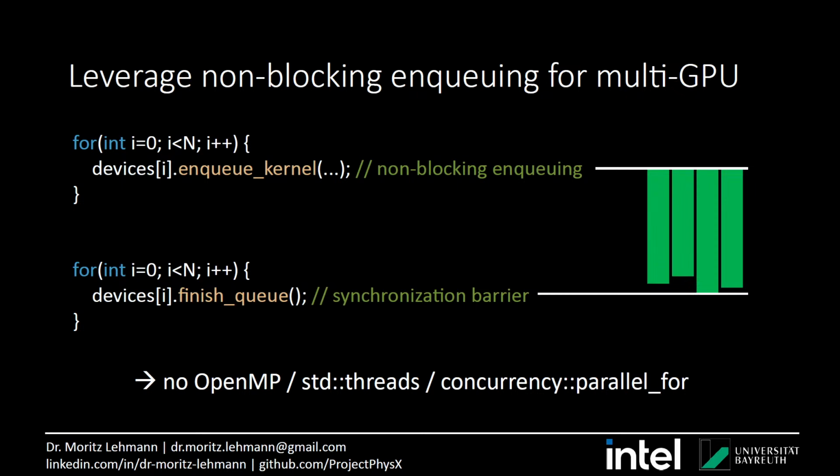introducing another subgrid with a very coarse discretization of D3Q7 to model thermal distribution functions. They are coupled to the lattice Boltzmann again over Guo forcing, because in parts where the fluid is hotter, it gets less dense with thermal expansion, and then it creates a local buoyancy force, which can create flow again. And the flow in turn moves around hot or cold parts of the fluid. So that's a two-way coupled extension.